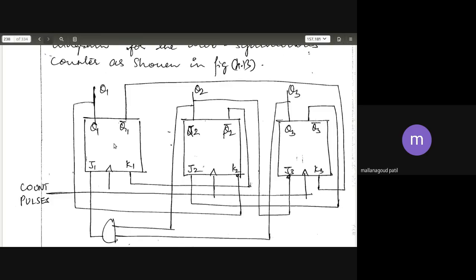Only if it is dynamic will you lose it. But in the static concept, you cannot lose that data. When you want to make it 0, you have to force it to write 0. Forcing to write 0 is clear. If you want 1 in the beginning, then force it to 1. Forcing to 1 is preset. Clear, make 0. Preset, make 1. Final conclusion.